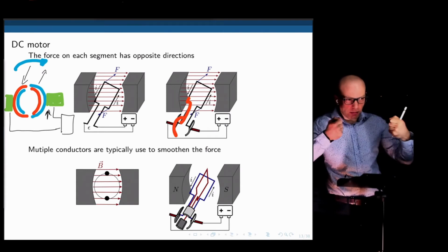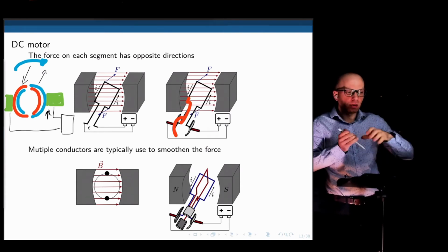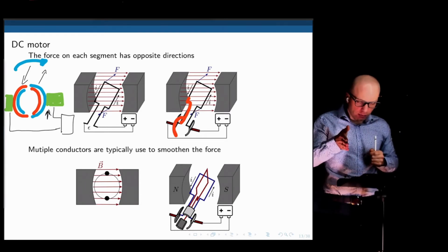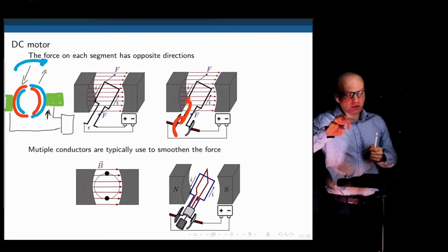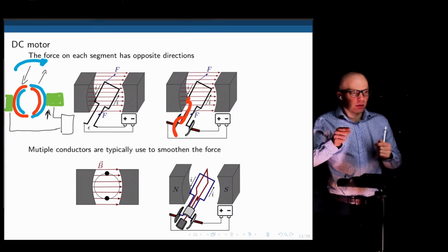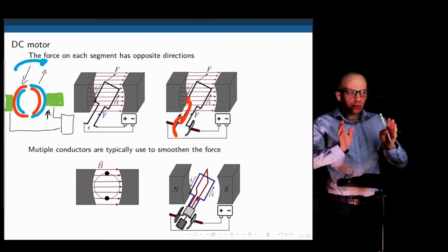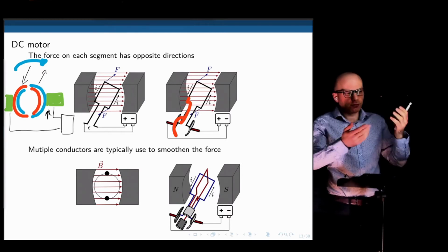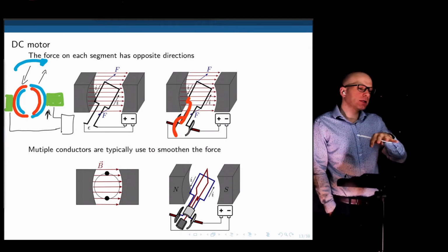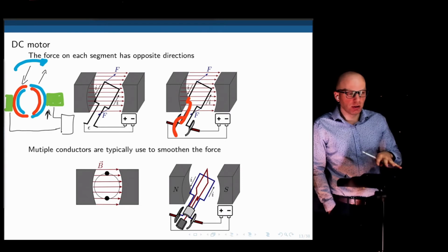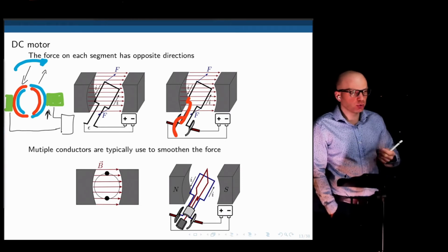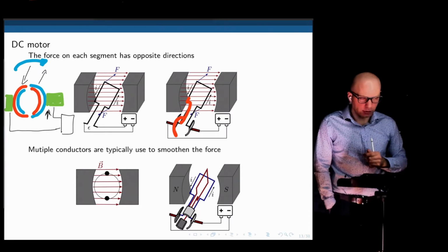All right, so these green parts are pushing against the rings, and as the ring rotates for half of the cycle, current goes in from the blue. For the second half of the cycle, current goes in from the red. And it will switch when you need to switch the current to ensure that the force goes in the same direction, right? So this is mechanically implemented in a DC motor or a generator. The encoder serves a different purpose. It's for control or speed or position measurement.